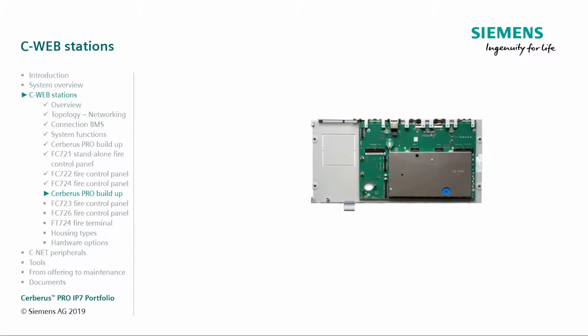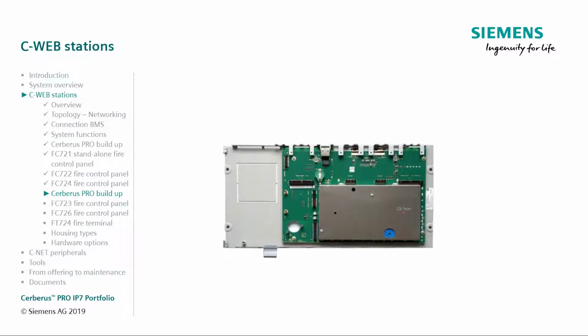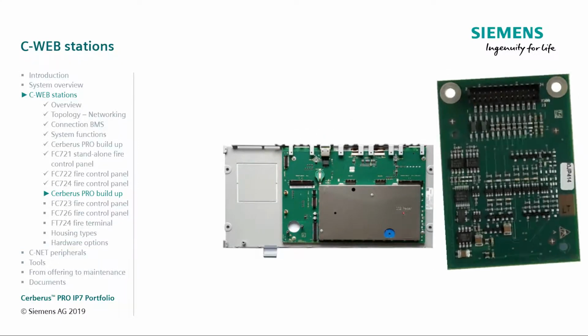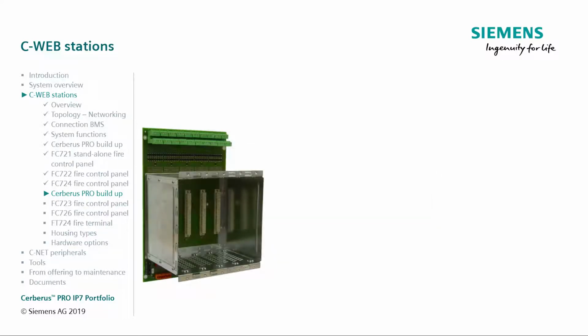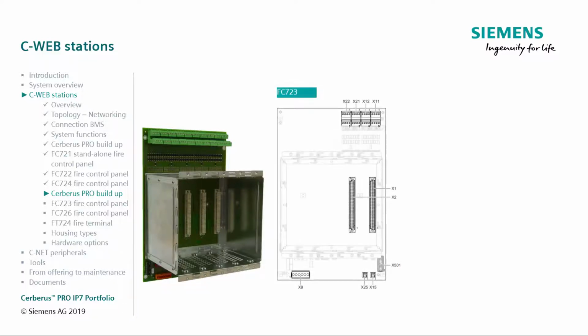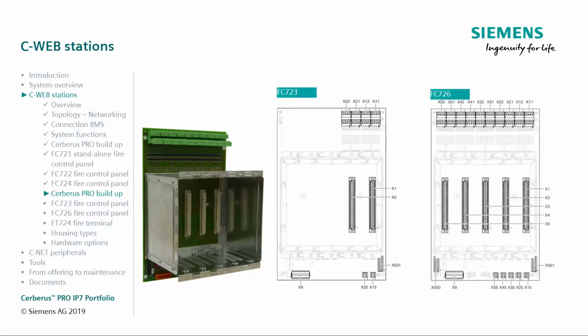So, how can we add extra hardware to our panels to increase the range of options? We just add an FC2006 to our PMI. This allows us to add a card cage. Simply connect the FCA 2006 via the X11 slot on the PMI mainboard to connect the card cages. There are two kinds of card cages, the FCA 2007 and the FCA 2008. The first one has 2 module card slots and the second one has 5 module card slots.